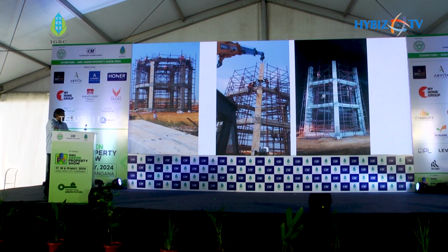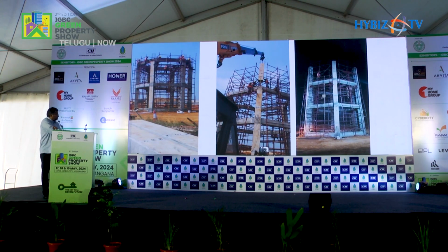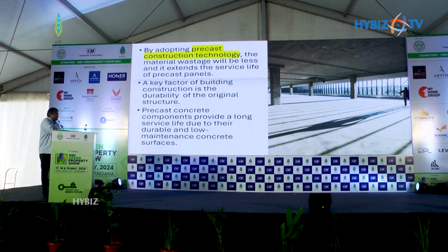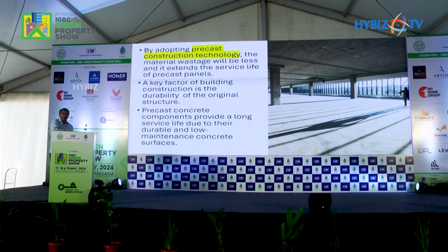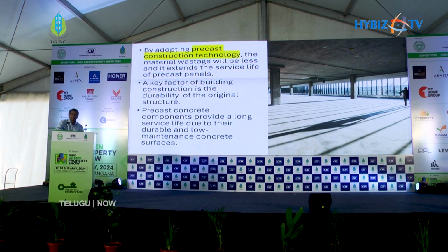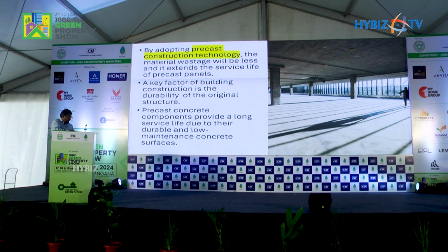This way they are saving a time of about 4 to 6 months, even for the water tank, which is something that we are doing for the Orissa government. With precast construction technology, wastage is less, and a key factor of building construction is durability. Most of the time, M40 concrete is what we adopt, because it is poured on the table and has to be lifted out the next day. So the concrete poured is M40, very high strength concrete, thereby it is durable and impervious. Only the joints between the walls are provided with non-shrink grout, which is stronger than M40; M60 strength is what we provide.